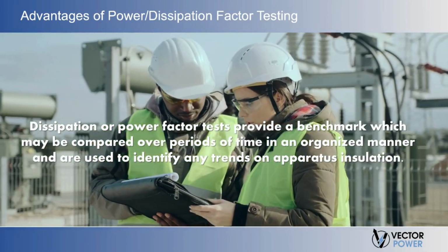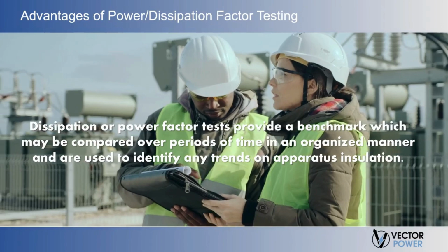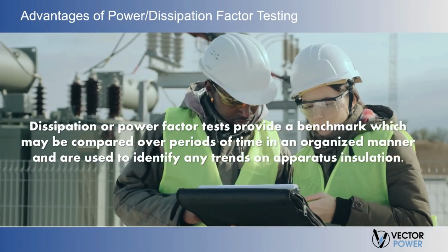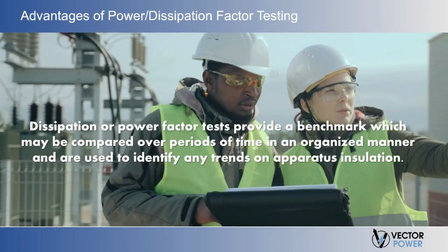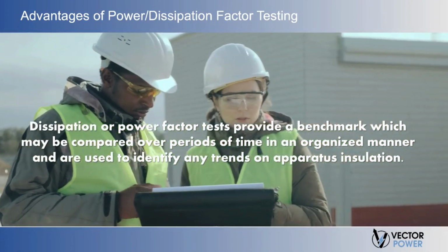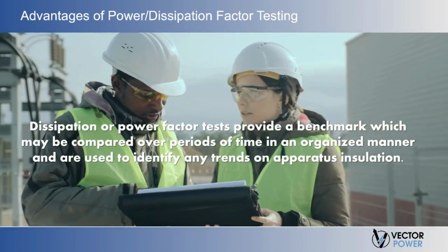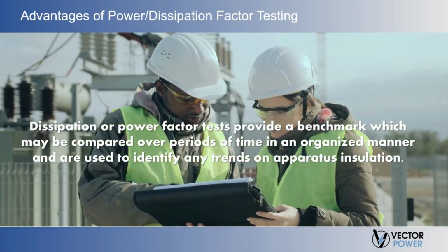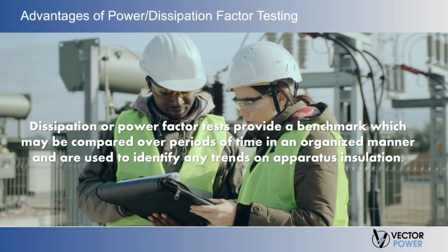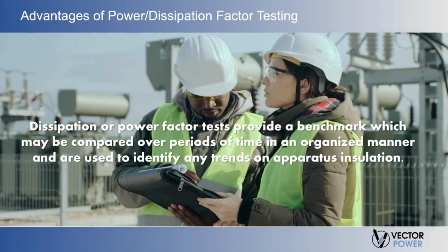Dissipation or power factor tests provide a benchmark which may be compared over time in an organized manner and are used to identify any trends on apparatus insulation. It provides a more complete picture of overall insulation conditions. Used in conjunction with capacitive measurements, it provides comprehensive data of the nature of the insulation.